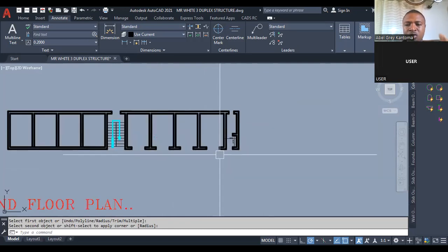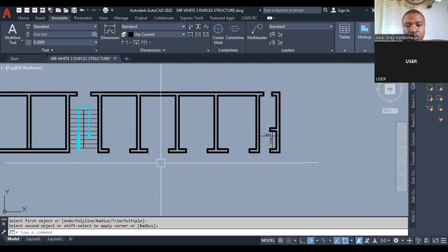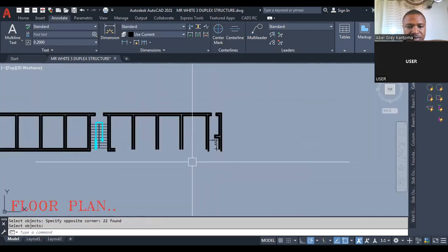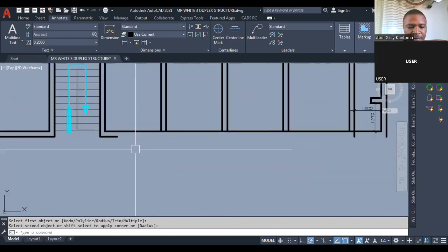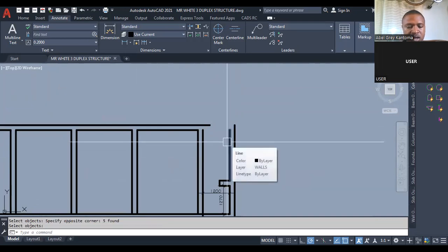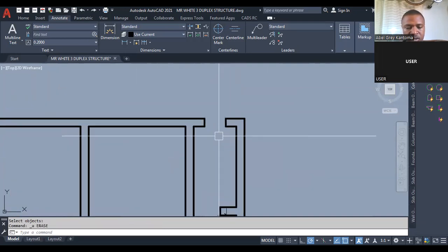So it's the normal AutoCAD keys or tools. You delete all of this by typing E to erase. I'll delete all of them. I'll use my fillets to fillet all of this. Fillet here, and then I fillet here. I'll erase this. So let me come back here.